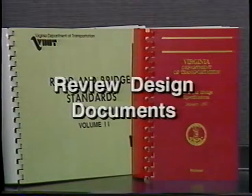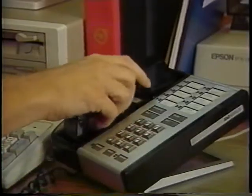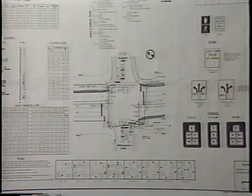First, you should thoroughly review all of the design documents. Next, prepare scale drawings of the location. And then, you need to arrange a field visit. A scale drawing of the location should show the correct geometry of the roadway and the exact location of the in-road sensor element in relation to the stop lines.